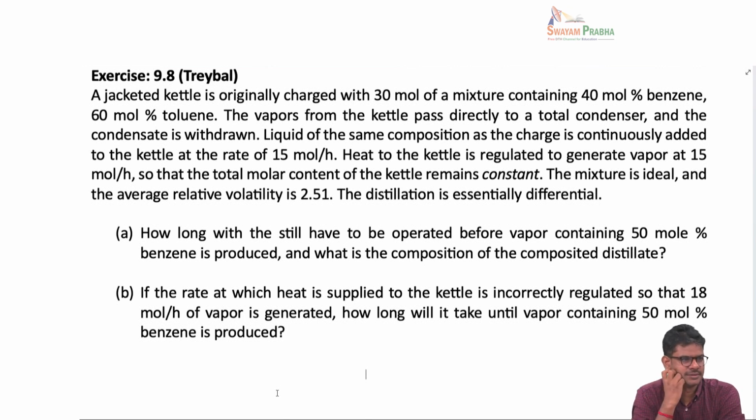Feed is, yes. So operationally, generally if you think about batch distillation or differential distillation, you start with an initial liquid mixture, and then you continue to vaporize. So as a function of time, the amount of liquid in the still will decrease, to the extent that you are vaporizing it.